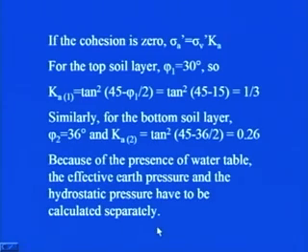As I told you when we were discussing the effect of the presence of a water table, the water exerts hydrostatic pressure. So, there is no need to multiply the vertical stress due to the water pressure with the coefficient of lateral earth pressure, because whatever is the pressure due to water in the vertical direction, exactly the same pressure will be there in the horizontal direction.